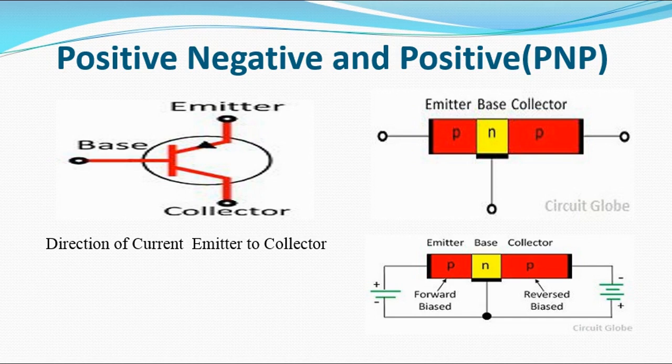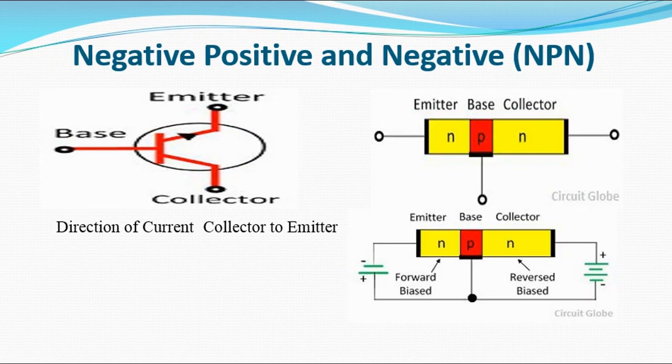Now, I want you to understand this. It means that the collector-base junction between the NPN and PNP are all connected in reverse bias. Look at this here. It is connected in reverse bias. Here is the collector base, here in terms of the PNP. Let me also show you the NPN. Look at it here. It is also connected in reverse bias. So that is to say that the collector-base junction, both the NPN and PNP, is connected in reverse bias. That is what I meant there.